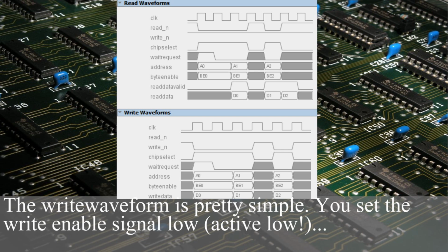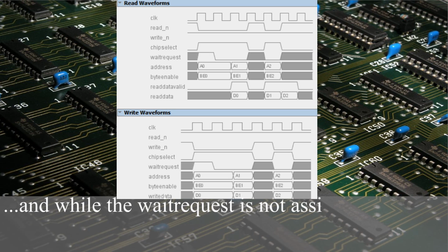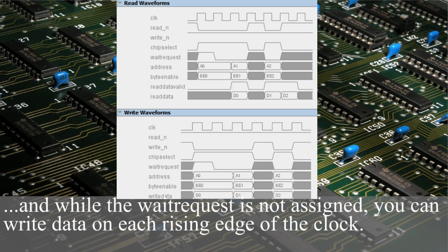The write waveform is pretty simple. You set the write enable signal low, and while the write request is not assigned, you can write data on each rising edge of the clock.